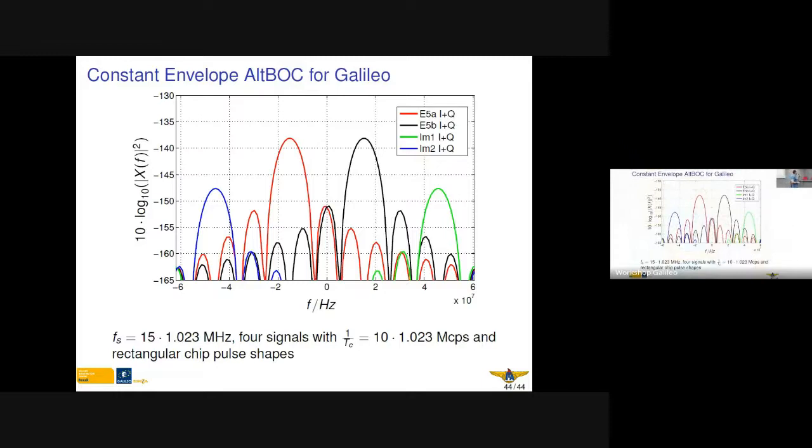And we have a power spectral density that can be achieved with this multiplexing. In general, we are multiplexing 4 different signals on one carrier frequency in the middle, but we have also achieved transmitting 2 QPSK signals on 2 different subcarriers. Yeah, and this is very interesting. We can also see here, in green and blue, the power spectral density of all these intermodulation products.